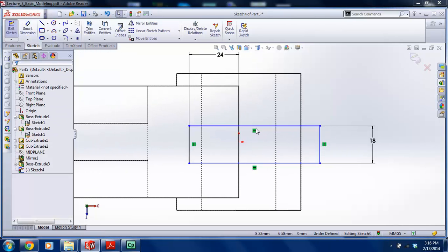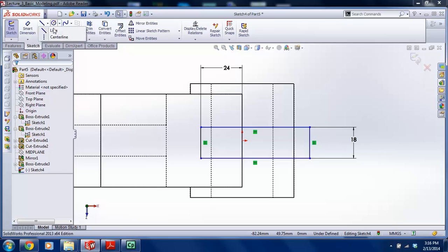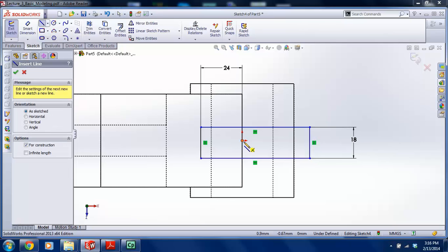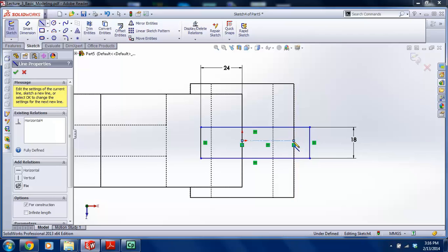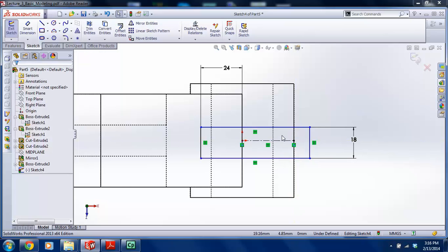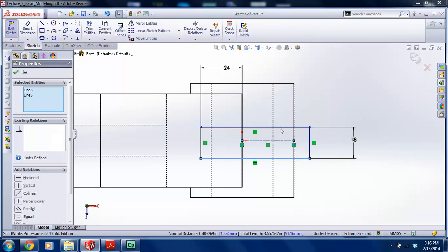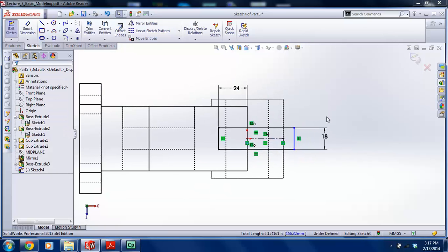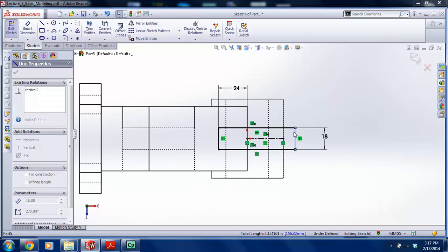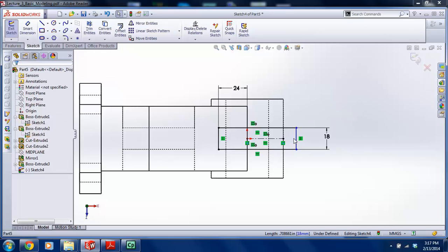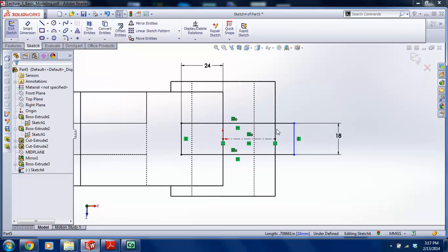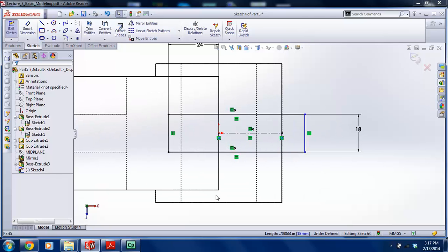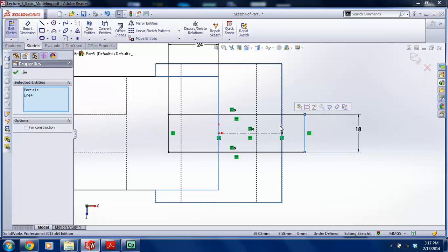Now, how do I center this up? Again, I put in a center line from the origin to here, and then I'll select the 3 lines and I'll make it symmetry, and that's it. Now, look, this line here, the proper thing to do is lock it in really with that circle there. Why is that? If you come back and have to change this, and this cylinder gets an awful lot bigger, what'll happen is that the cutout will follow it.